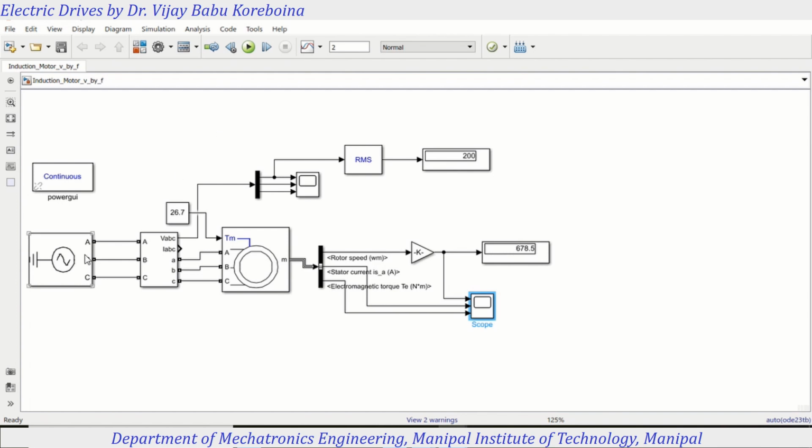We have an AC supply, 400 volts, 50 hertz, and we have given that to the motor. The motor will run at the standard RPM, 1434 RPM, fine. In order to have variable speed, we need variable voltage and variable frequency. But how do we get that? We don't have a direct variable voltage and variable frequency supply to give to the motor. We have a standard voltage and frequency fixed by the supply, that is 400 volts, 50 hertz.